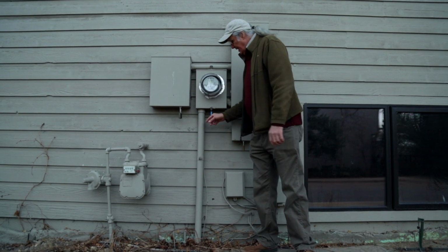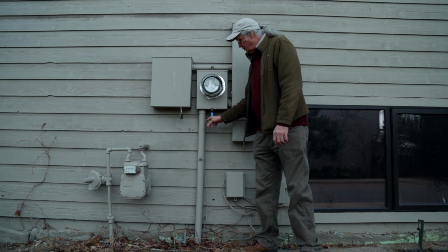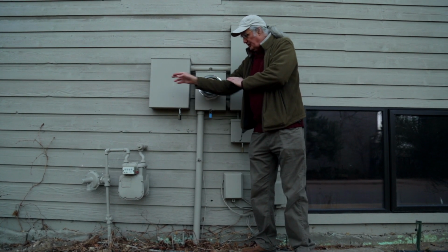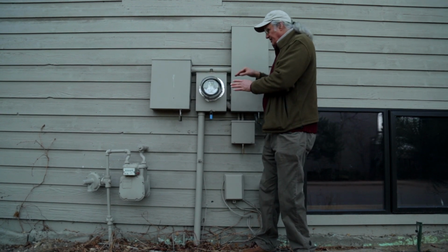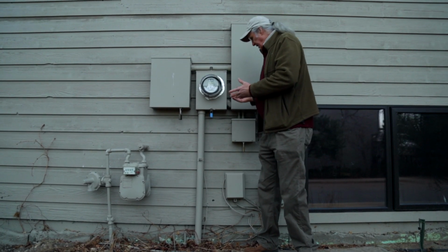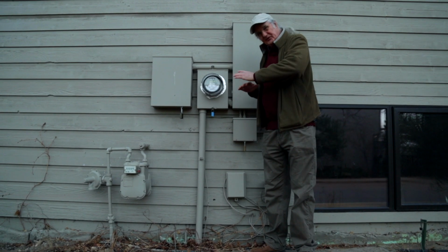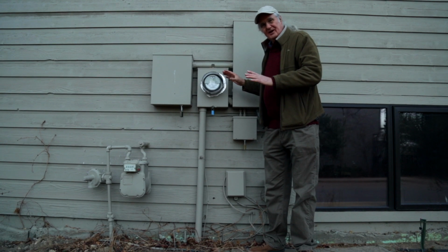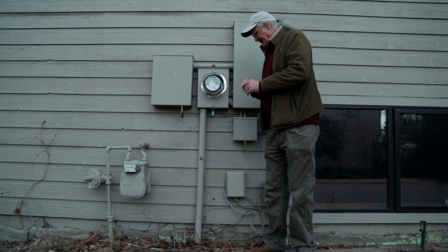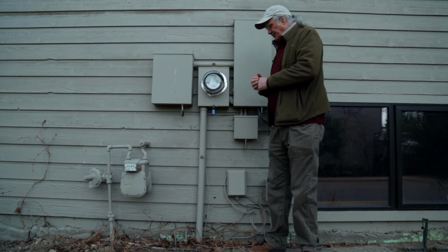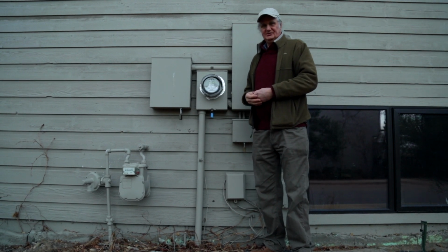If not, what happens is there are magnetic fields that come from the current that flows on the grounding wires to the water pipe, which could be on the other side of the house, which is the case here. It's down in the basement, or to the TV cable, which may come in here, which does, but it could come in on the other side of the house. So then you have this current flowing on these grounding paths inside the house or through the house to get to the egress on the other side, to the water pipe or the TV cable, and it causes magnetic fields in your house. Fortunately, that's a fixable situation.